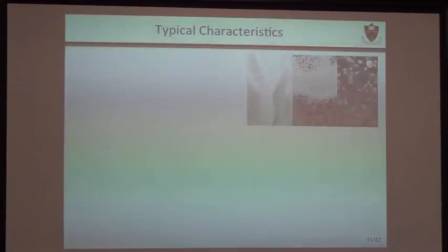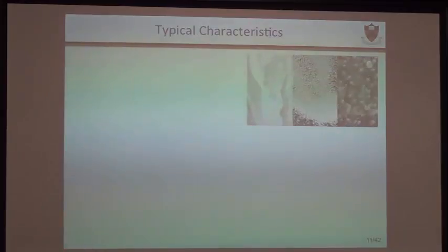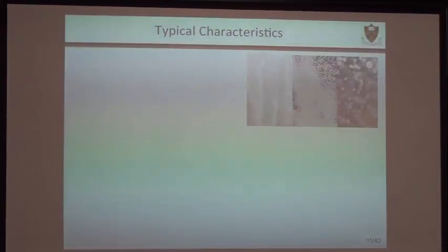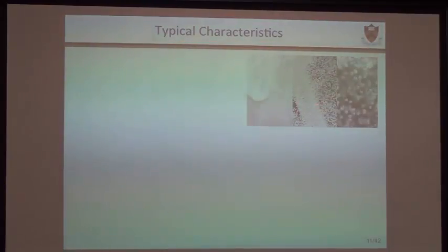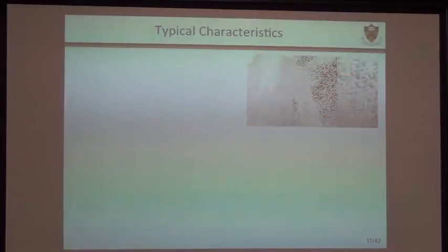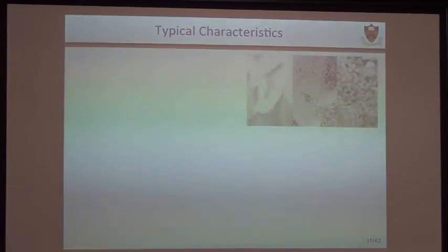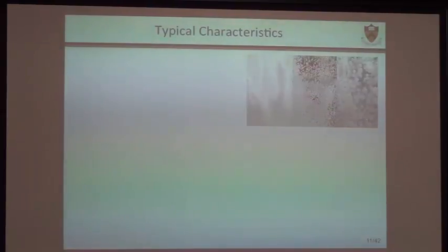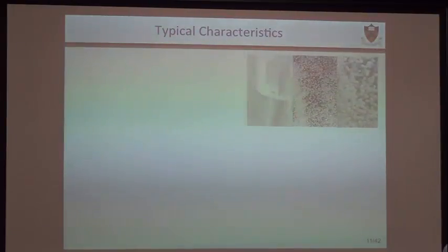These were taken with somewhat larger particles for visualization purposes. People are really interested in finer particles, which are more typical of what we do. So you start seeing these kinds of flow structures. Some of these finer-scale flow structures are of the order of 20, 30, 40 particle diameters. If you are working with 100 micron particles, a 40 particle diameter structure is of the order of a few millimeters, and the vessels are often of the order of a meter.